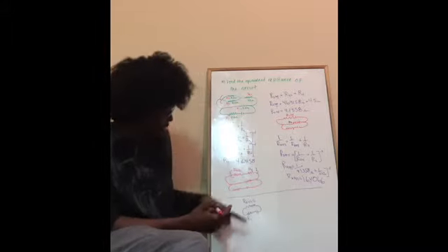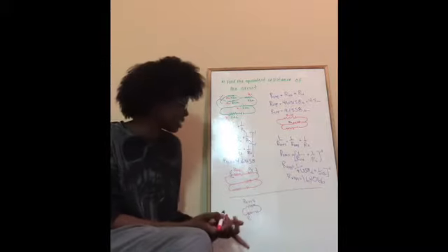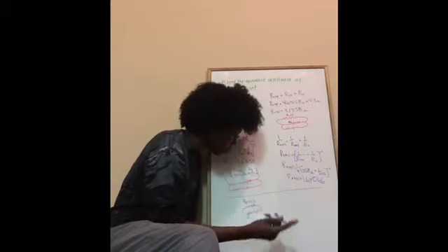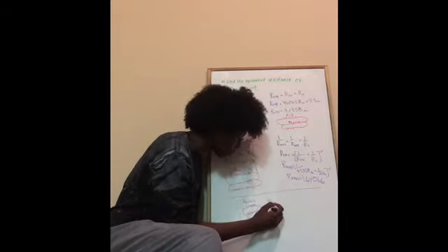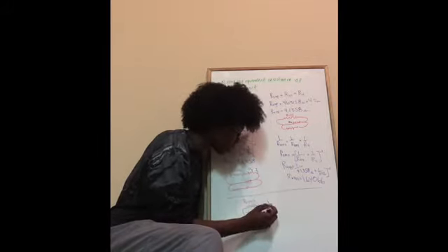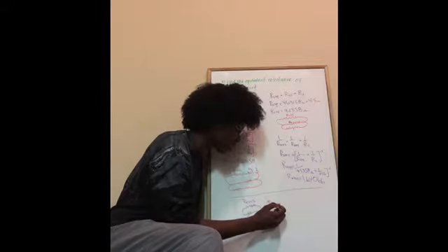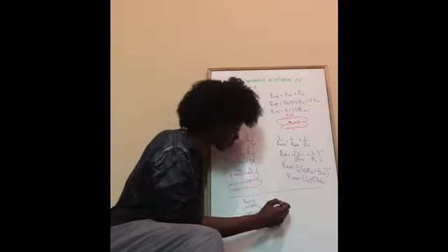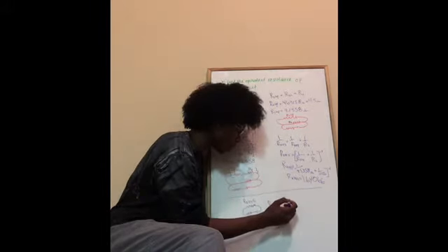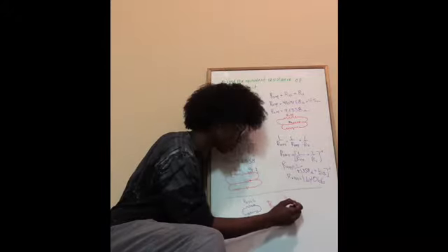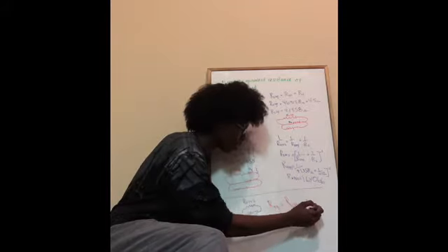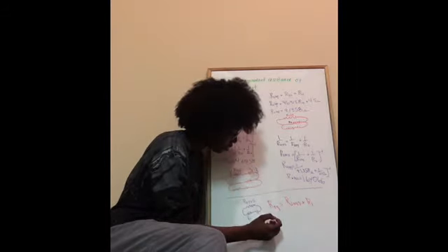So last we're going to combine these. They're on the same exact loop, so they're actually in series, so it's going to be very simple. It's going to be our R equivalent, because all of our resistors are equivalent to each other. R equivalent is R2,3,4,5 plus R1. All right, and then we're going to implement our values.